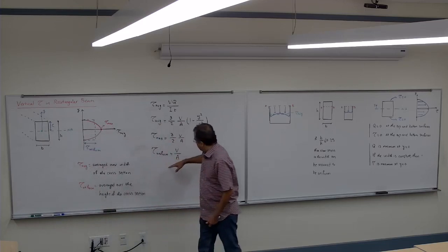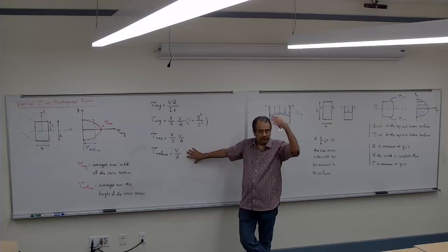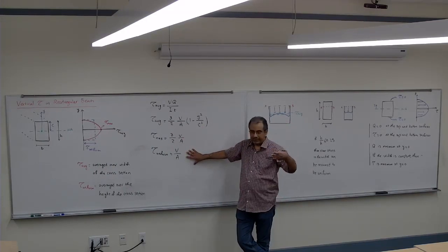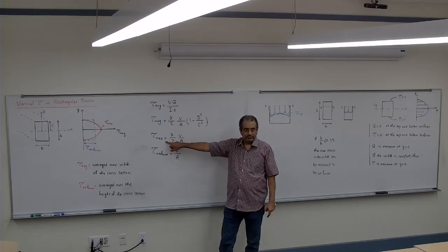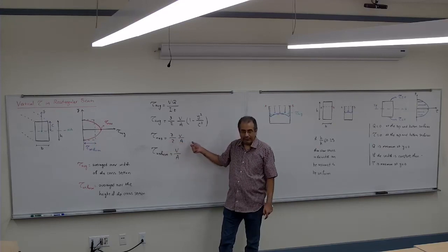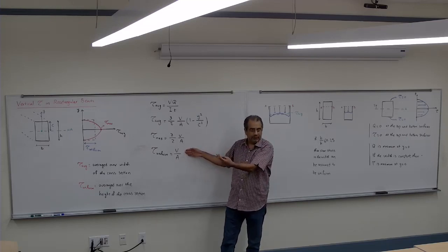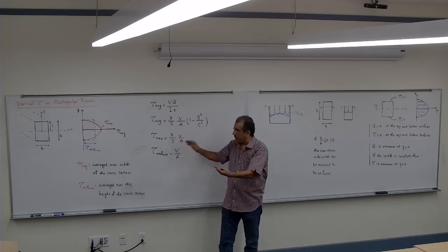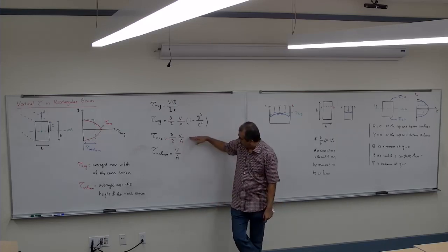Look at here. This is the equation we have been using up to here. Shear force divided by area. So the shear stress is shear force divided by area. Compared to the maximum, it is 50% less. So we used this equation from the beginning because it was very simple to understand. But if we use that equation, we underestimate the shear by 50% in the cross section. So we have to design for the maximum, not this.